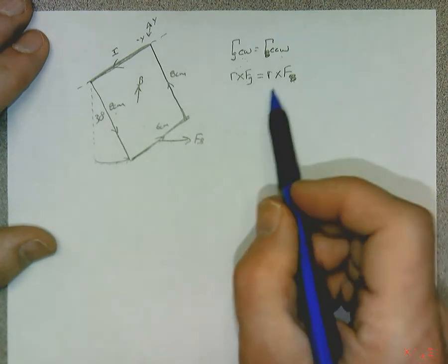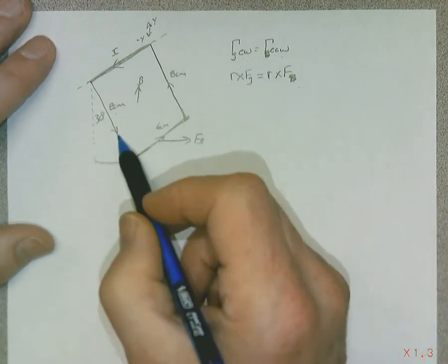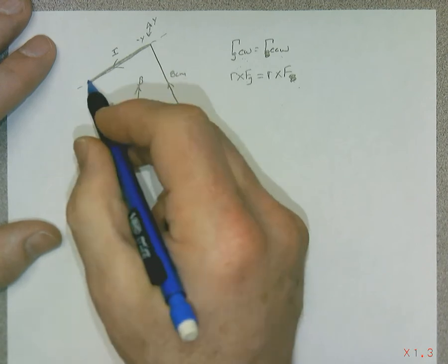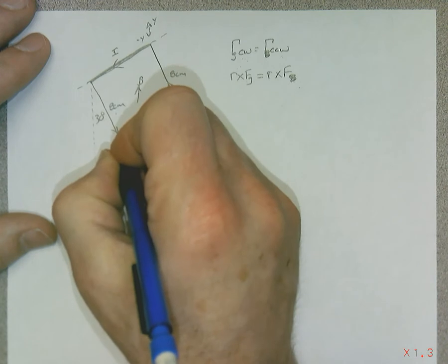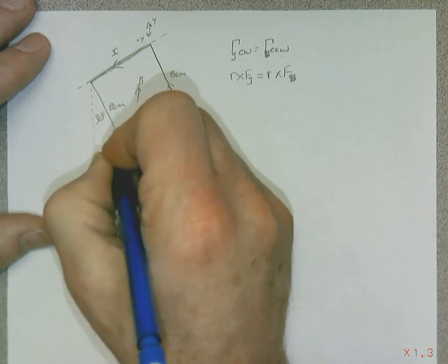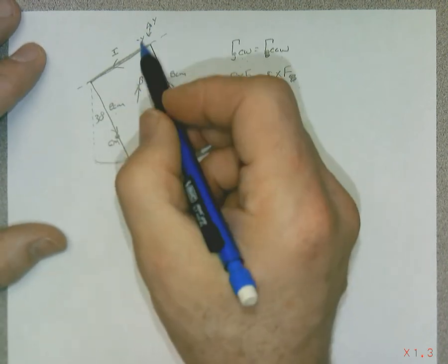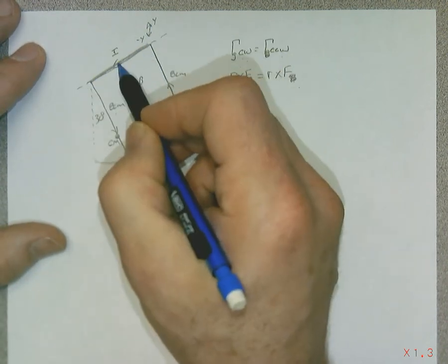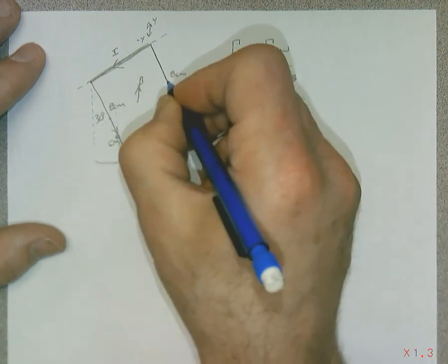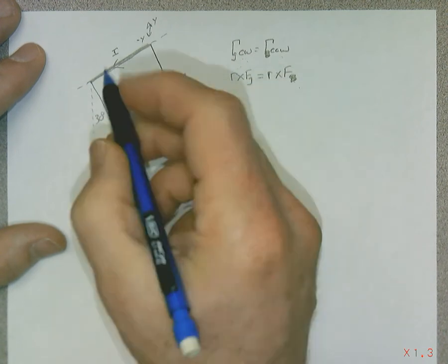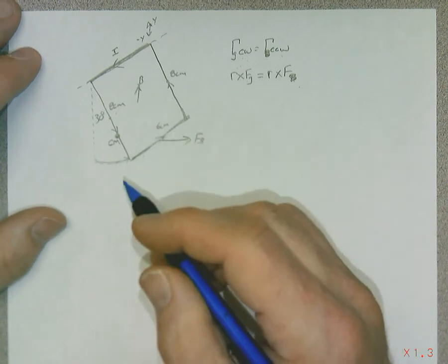So to carry this out now a little bit more, we're going to do the gravitational torque. And if you remember, we got 3 segments here. So what's the gravitational torque? Well, what we got to do is actually find the center of mass of this system. Now, since it's pivoted from this point, this chunk doesn't matter, but these 3 chunks do. And these 2 have a center of mass at 4 centimeters with respect to this pivot point, and this one is at 8 centimeters. So we need to put that together.